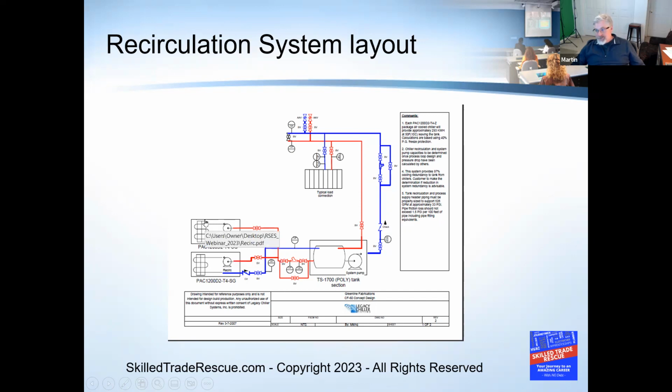Talking from a refrigeration standpoint, that's also beneficial for your refrigeration, because as you guys know, if you've got a TXV, because most of our stuff was TXV, either an EEV or a regular mechanical TXV, if these evaporators saw a big spike in their approach temperature, let's say we originally sized them for 50 degrees approach coming in on the inlet of the heat exchanger, and for some strange reason now it's 60, the design is a little out of whack.